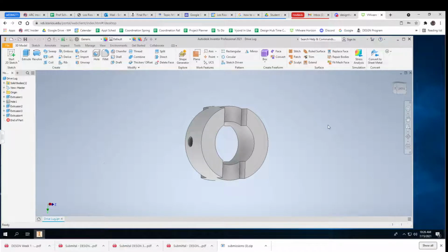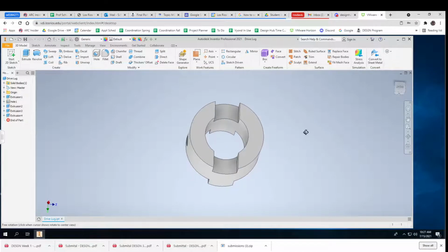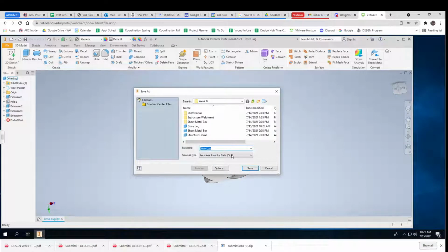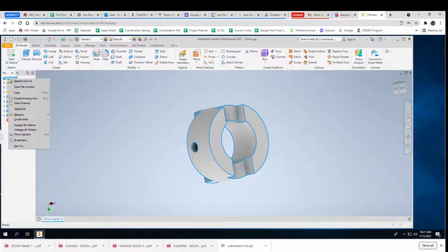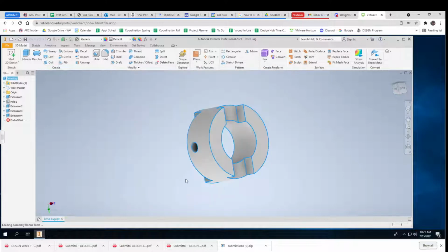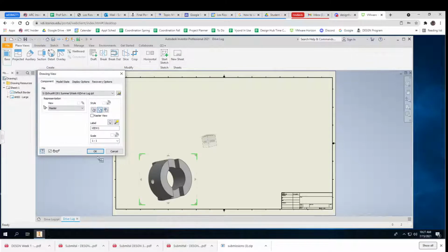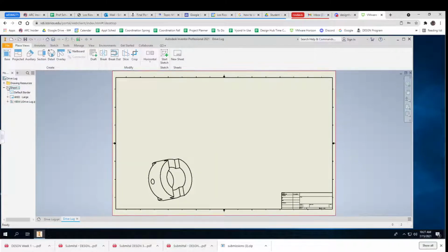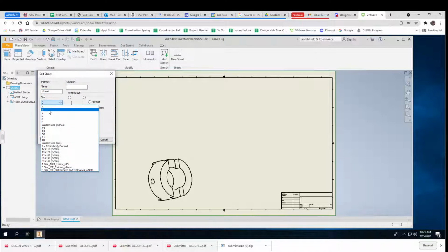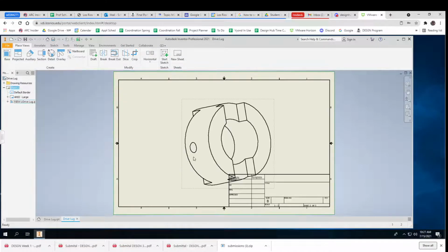Okay, so now I'm going to go ahead and make the drawing. So I'll come up to the top, right click, and create a drawing view. Now, the sheets as they come in are huge. The default is a D size sheet. So once it's in there, I've got to double click and right click, edit sheet, and make it a B size. Probably even an A size would be fine.